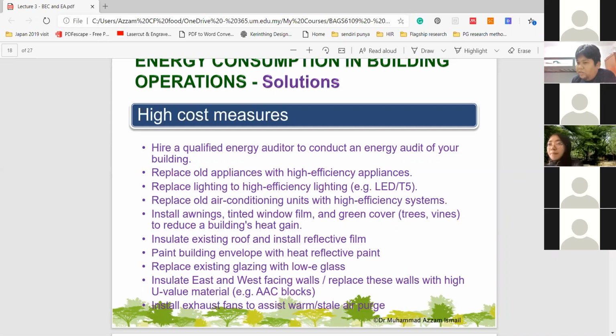Because usually flushing of the aircon system only happens once, just before the building gets opened during the building commissioning period, just before handing over to the client. And after that, no more flushing. Why not? You're supposed to be flushing it, but most of the time people don't flush the aircon ducts. To them, it's just a nuisance, extra work, to clean up something.